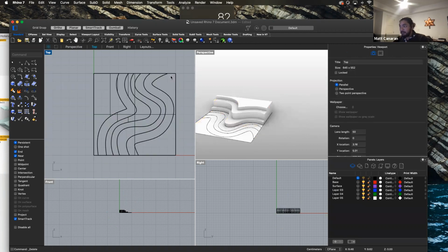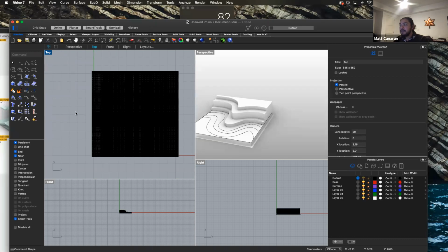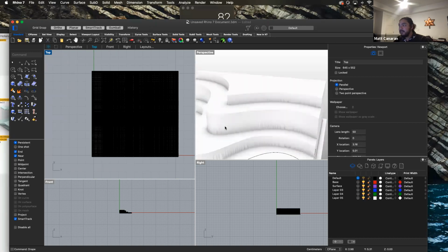Let's go back and change the parameters of drape a little bit because I want to change the undulation of the cloth. So I type in drape, hit enter. Let's change spacing to 1. Let's see what happens. And then I'm going to drag over this area again. See how the undulation has changed to make it a lot softer and smaller.